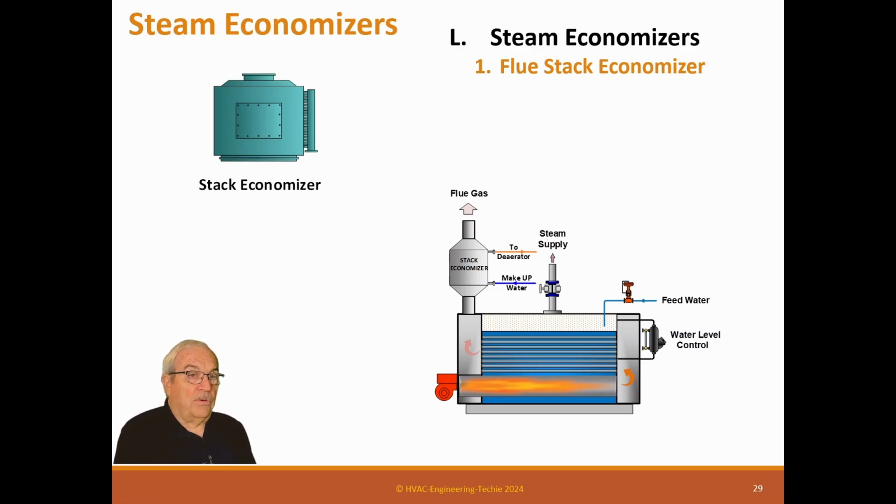This is always important. The two things in efficiency in a steam system is, one, maximum condensate return. Every drop or every pound of condensate you don't return, you have to make anew, which takes more energy because condensate's normally hot. It's right around 200, 212 degrees, right below steam generation. So it's normally hot. So that you want. You want to get as much of that as you can, and you want as hot a feed water as you can get. And that includes economizers to pump up the temperature of the feed water. Captures flue heat for feed water.